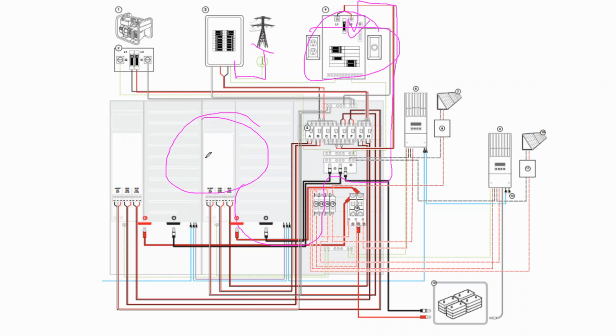That's why at the residential level, you commonly see battery inverters with a critical load panel outlet built into them to feed a very small, maybe 2 kilowatt, critical load panel.